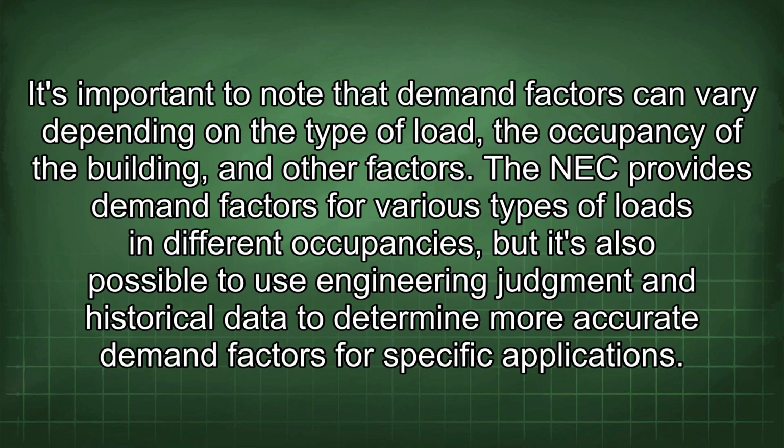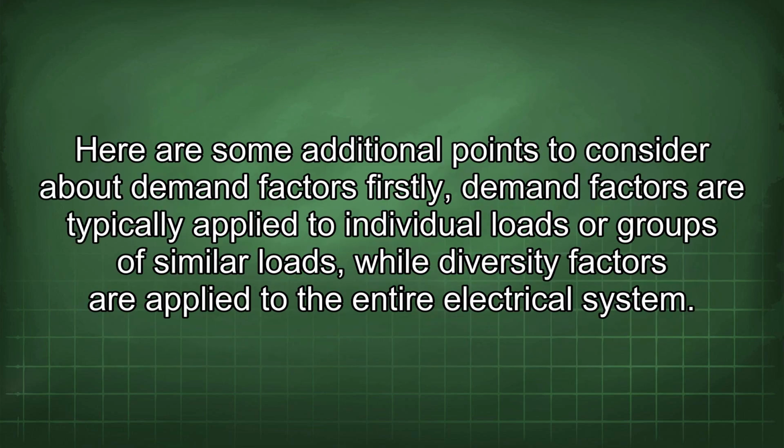It's important to note that demand factors can vary depending on the type of load, the occupancy of the building, and other factors. The NEC provides demand factors for various types of loads and different occupancies, but it's also possible to use engineering judgment and historical data to determine more accurate demand factors for specific applications. Here are some additional points to consider about demand factors.